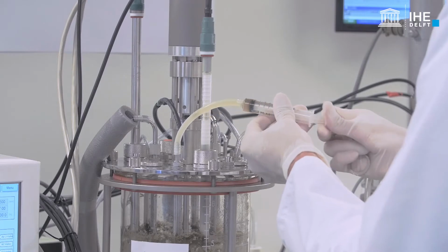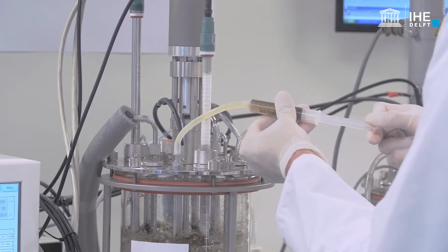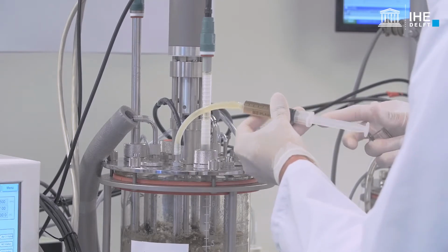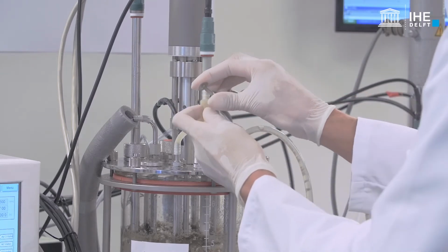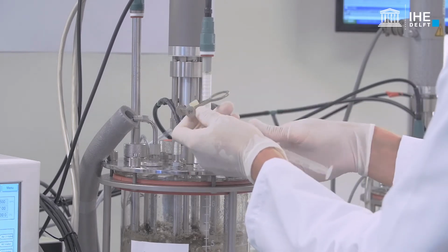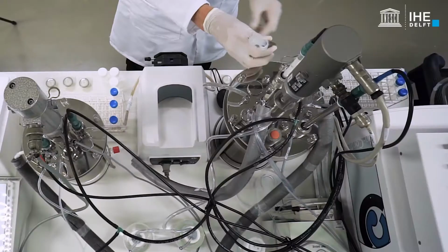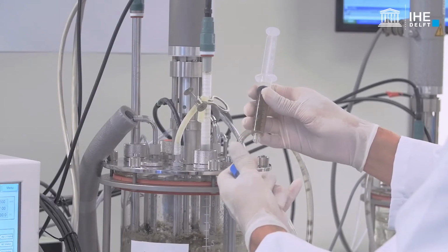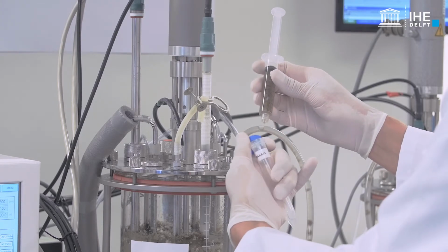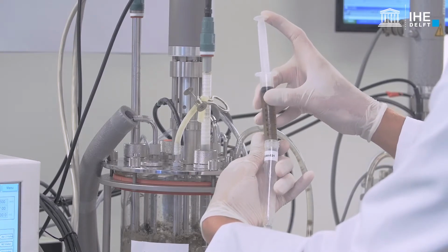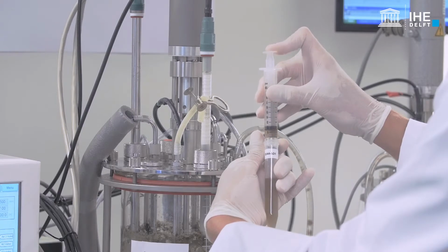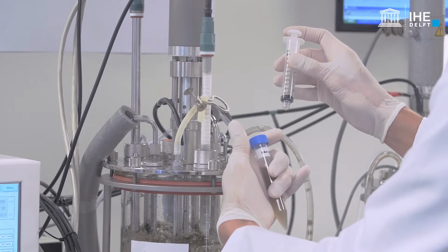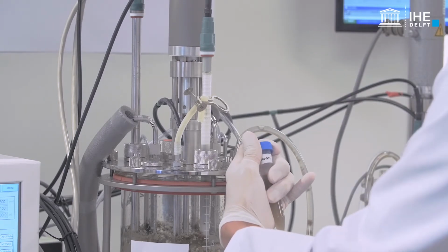By the end of the anoxic stage in Reactor 1, collect by triplicate the corresponding samples for the determination of PHA and glycogen contents. Follow previous recommendations for the collection of these samples. Their collection is essential to determine the conversions of intracellular compounds in the anoxic stage executed in Reactor 1, and thereby to determine the stoichiometric ratios of the anoxic conversions.